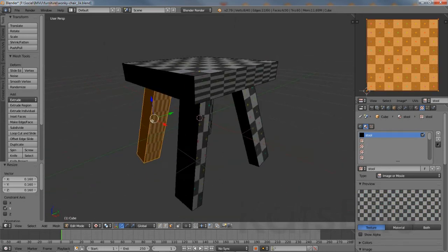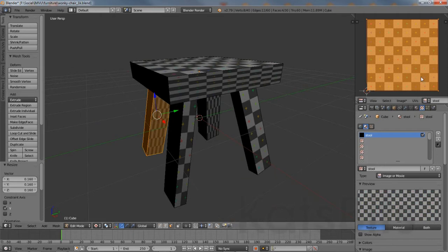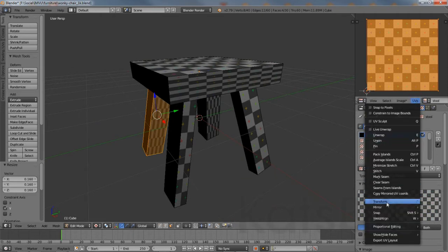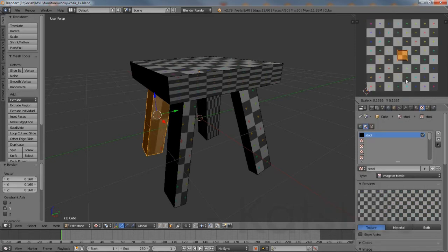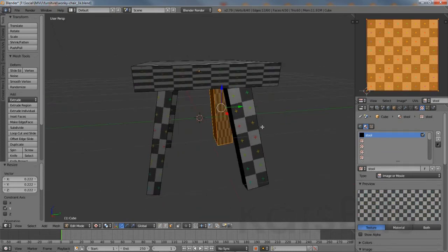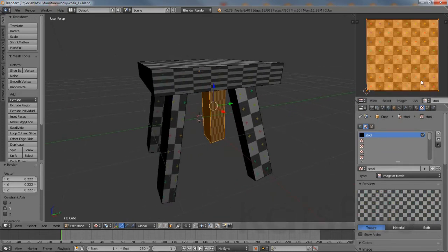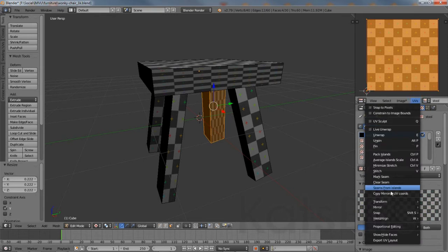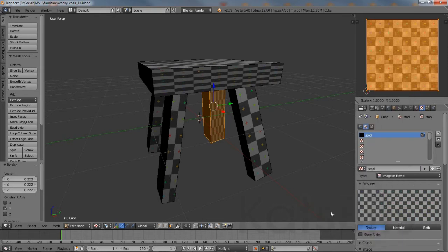Right-click, shift right-click to make a selection in the 3D view. In the UV image editor, left-click UVs, transform, resize, then press Y or X to lock the appropriate axes, left-clicking to confirm each change. When making multiple selections, make sure to complete a given scene manipulation action beforehand to prevent accidental selection. Middle-click drag to rotate, release, then shift right-click select.